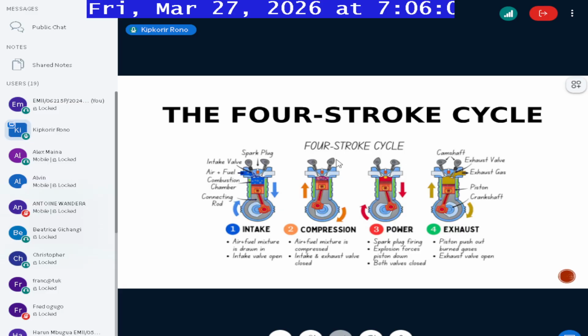So the flywheel, because of its mass and geometry, contains potential energy, and it's connected to the crankshaft. So during starting, that potential energy is normally converted into kinetic energy. And that kinetic energy is the one that pushes the piston up and down during intake, compression, and exhaust. It's only in the power stroke that the piston comes downwards without any form of assistance.